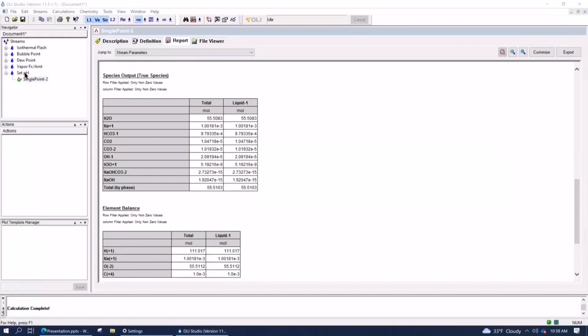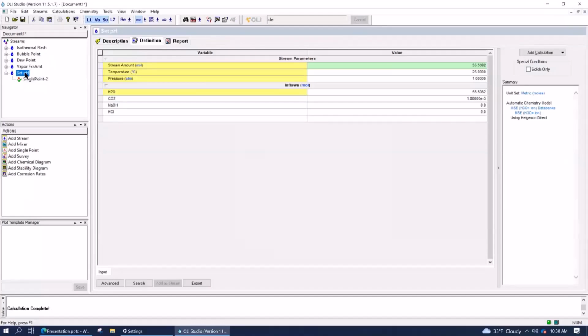We don't have to do a set pH, but we are going to do acid-base chemistry, because that's what you're describing. We're going to make it 4 phases: a vapor phase, a hydrocarbon phase, the water phase, and a potential solid phase if one forms, probably not. We're going to add CO2, H2S, methane, and maybe a decane to the system. The CO2 and the H2S are going to partition to the 3 phases. Then we're going to add a little bit of MEA and see how all those components partition across the phases. Very simple case.